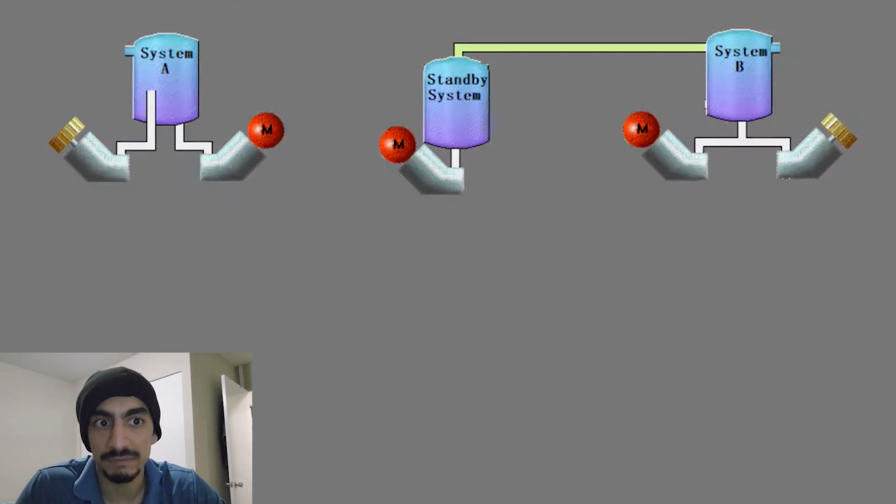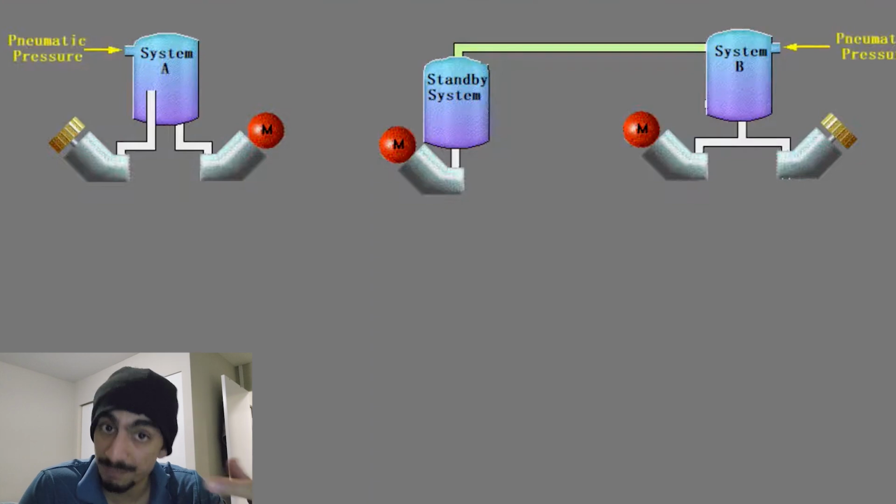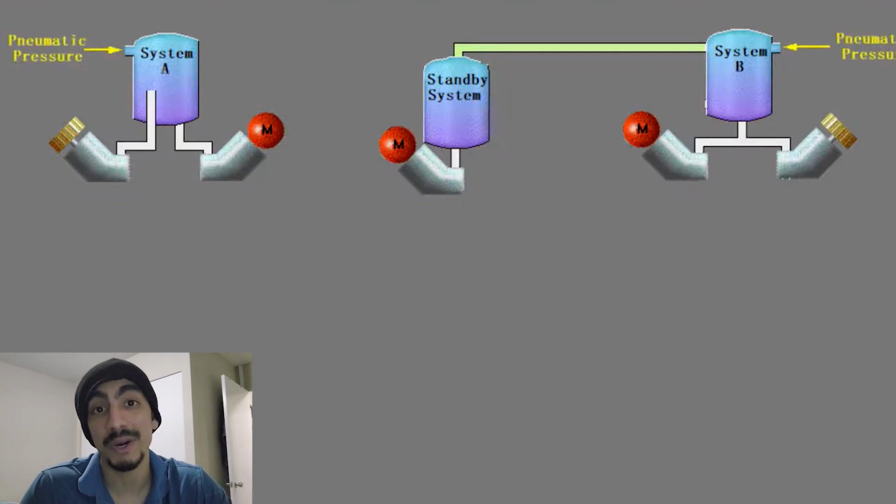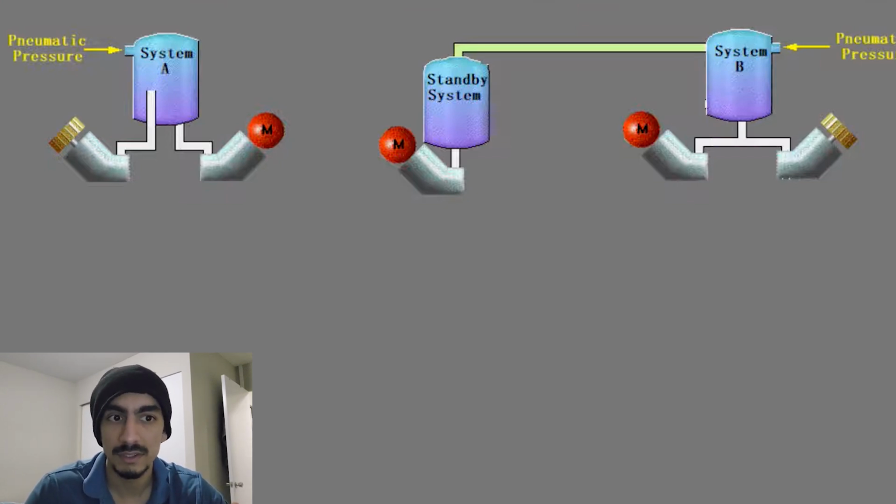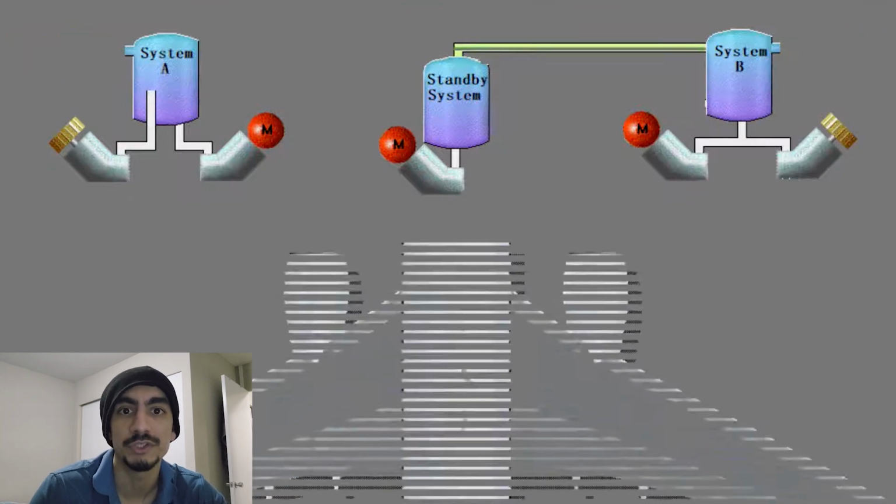So the engines of the aircraft typically have hydraulic pumps attached to them, and as the engines spin, the pumps pressurize the fluid up to thousands of psi. Think of it like a super strong water gun, but instead of water, it's fluid designed specifically for extreme temperatures and pressures.